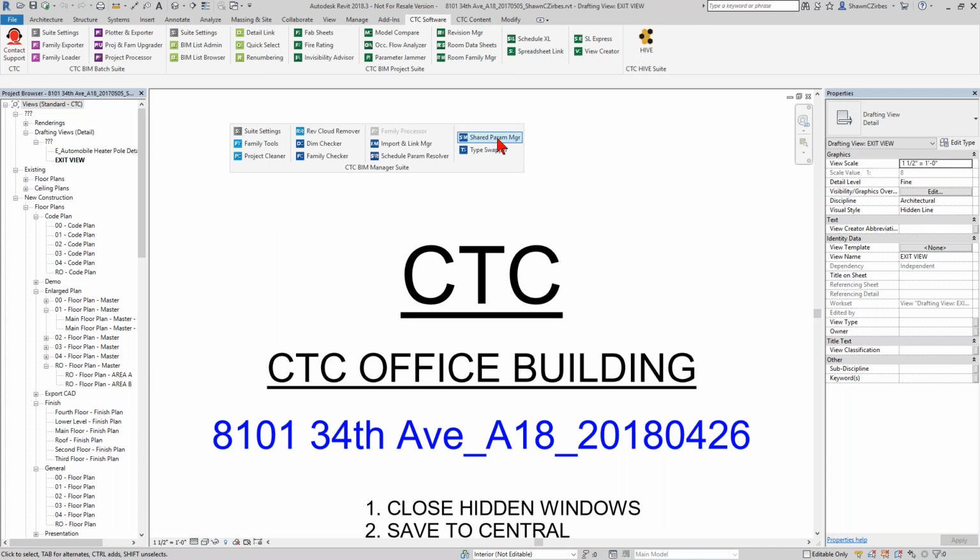you with this. There's a tool here called Shared Parameter Manager. There's a tool called Family Processor, the one that's currently grayed out. There's a Schedule Parameter Fixing tool here, Schedule Parameter Resolver, and there's also family tools to help do a little bit of cleanup on your library, a free tool over here. So with those four tools, I can actually go through and in a morning establish my standards or change my mind on some standards and implement those changes across my entire firm.